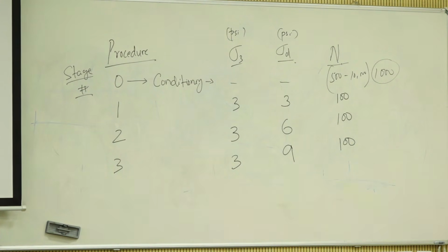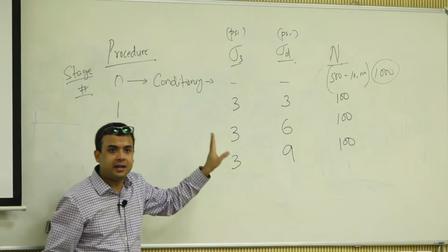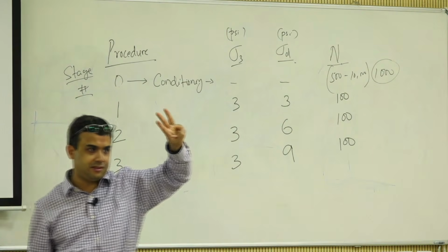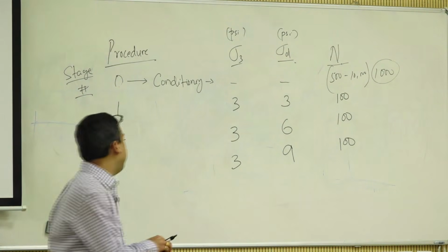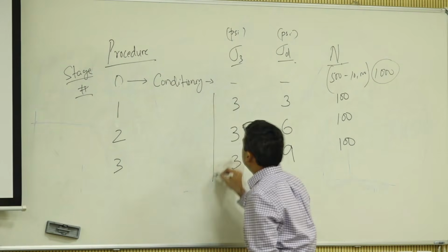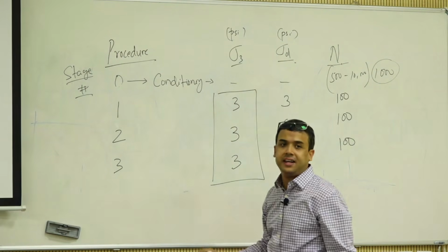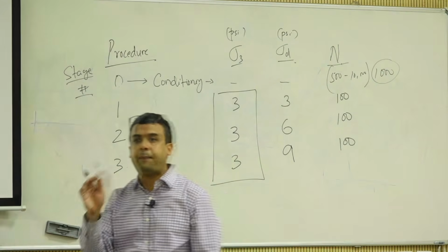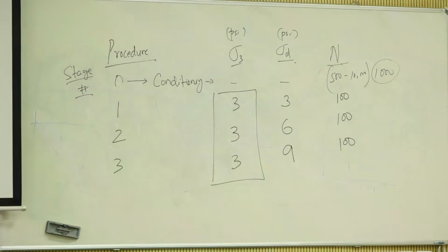There are 15 such sequences. We'll look at the values, and in the tutorial today we'll look into that too. So after conditioning, the test right now has 3 sequences, and during the sequences, what did we do with the confining pressure? Kept it constant. Hence the test is called CCP, constant confining pressure.